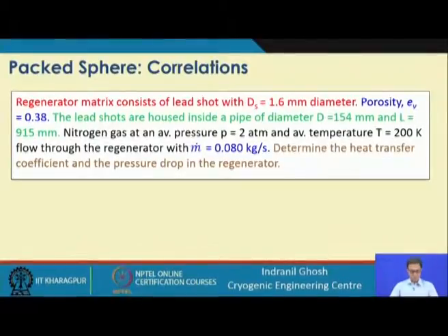So, what we need to find out is the heat transfer coefficient and the pressure drop, which is necessary for any regenerator design. When we talk about regenerator simulation or design, we will find that these two parameters will be essential to estimate the design, or to simulate the regenerator. So, let us first concentrate on this packed bed with the spheres and this particular problem.